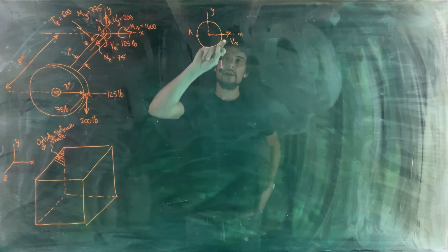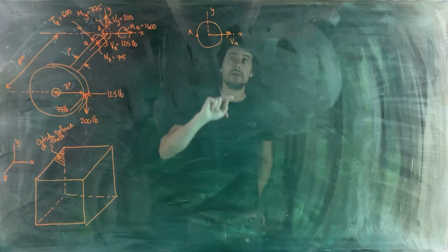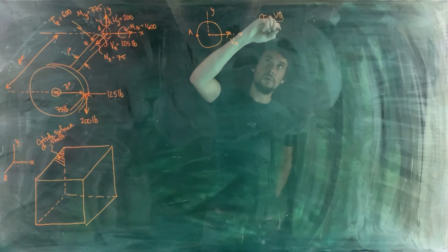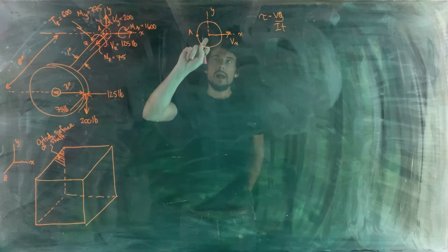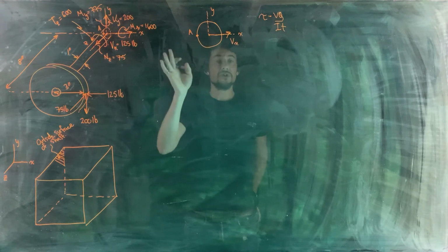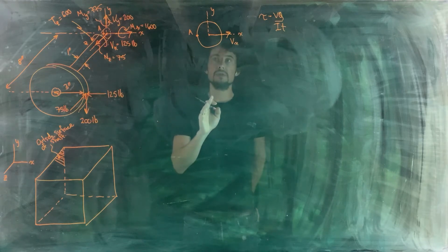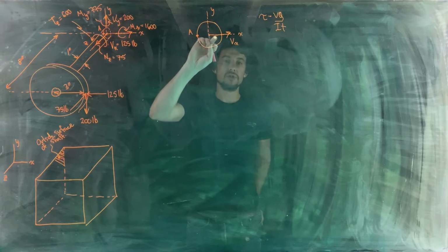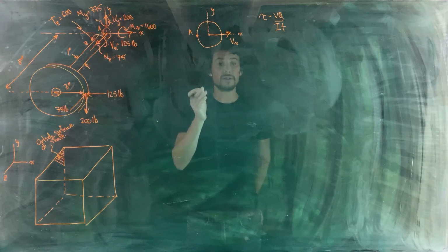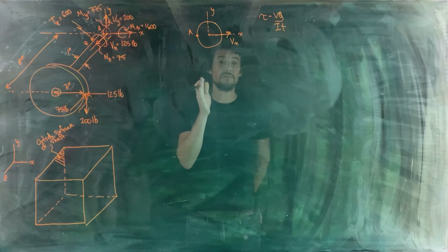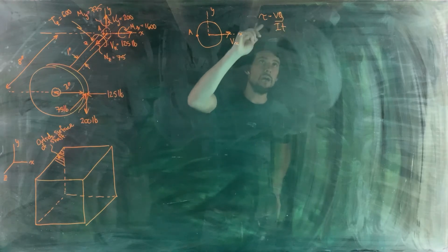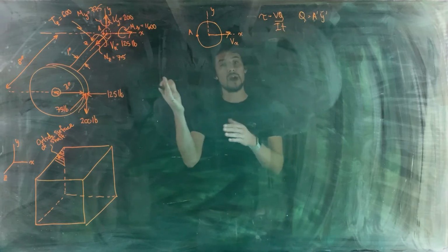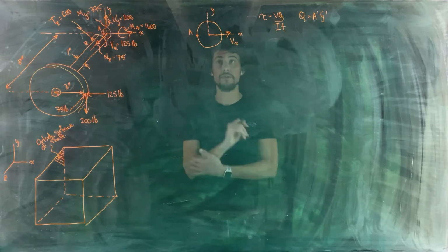We know that internal shear forces cause shear stresses, and we calculate these using the equation tau equals VQ over It. When you want to calculate the shear stress at any point, you draw a line through the point of interest that is perpendicular to the direction of your internal shear force, and all the points in the cross-section along that line share the same shear stress. For area A prime, which is part of Q, you take the area on one side or the other side of the line that you've drawn through the cross-section.